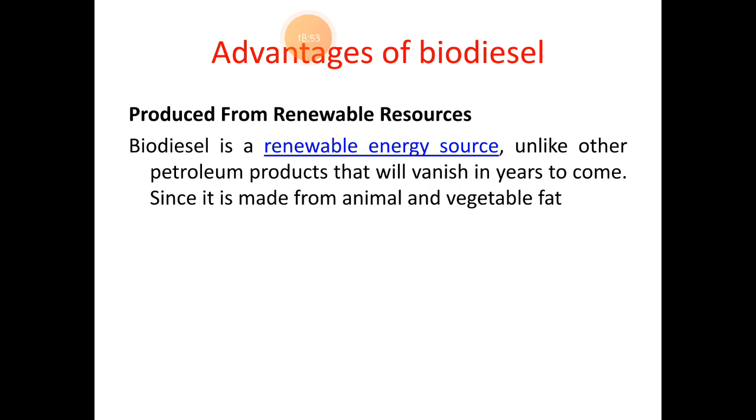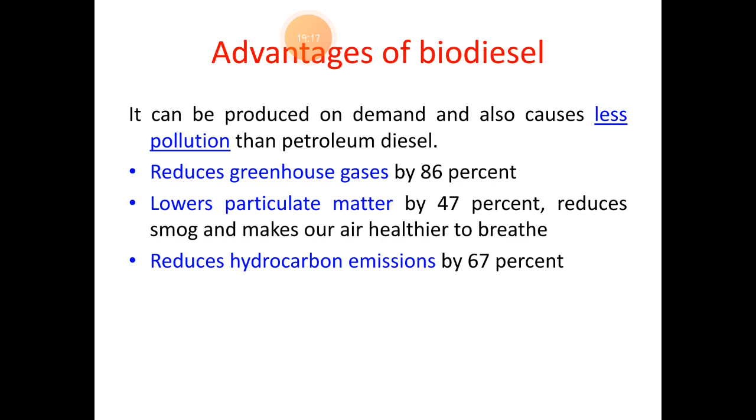It has the highest energy in it. Next is advantages of biodiesel. It is produced from renewable resources like vegetable oil and animal fats, not like the petroleum products, which take years of time for the degradation. Then biodiesel emits fewer pollutants, reduced greenhouse gases of 86%, then reduced particulate matter, that is of 47%. So the air pollution it causes is lesser compared to the fossil fuel diesel. It also emits 67% of hydrocarbons only.